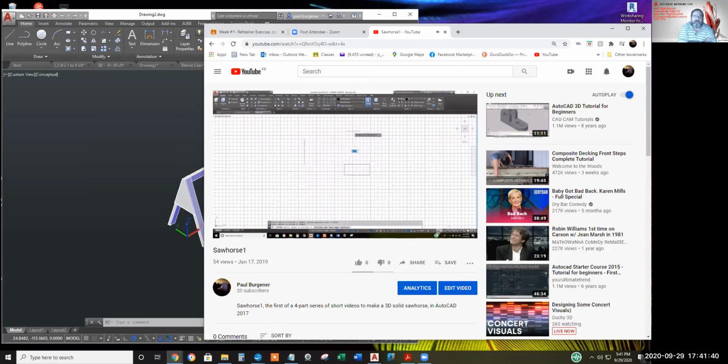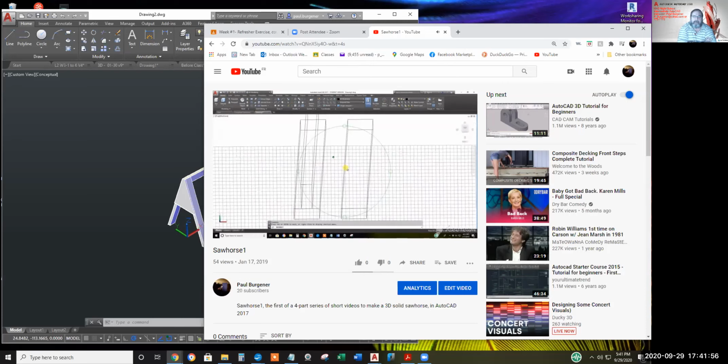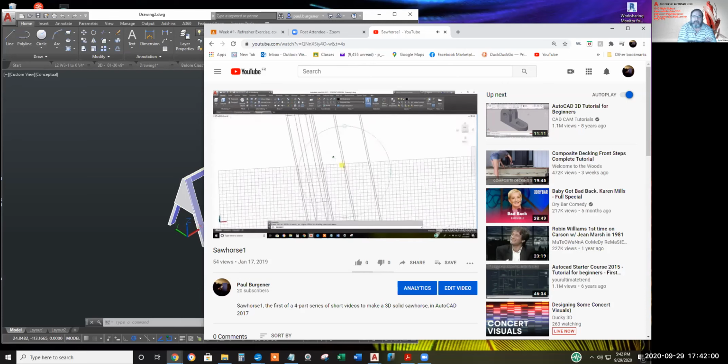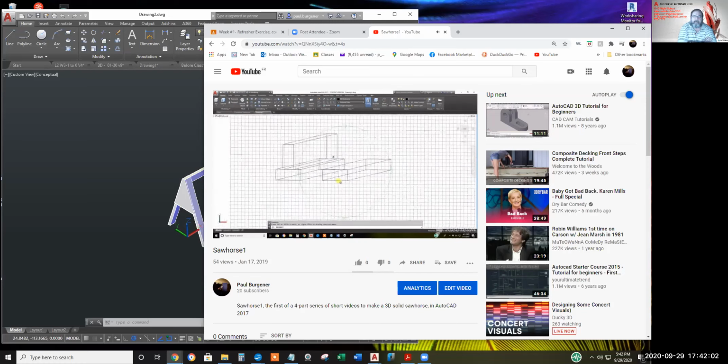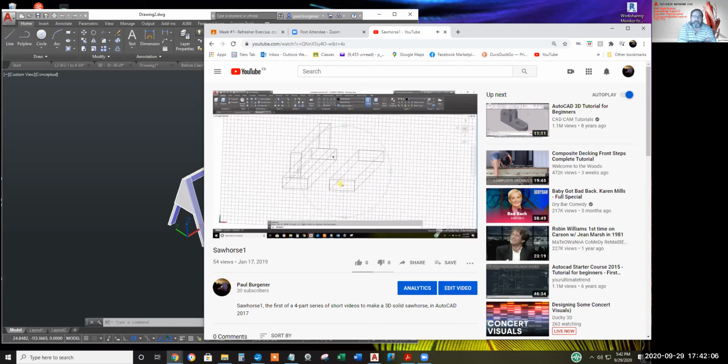You can also hit Enter by right-clicking and selecting Enter. Enter. 48 inches long. Free orbit. Now these three 2x4s stick straight out of the XY plane. Their ends are touching the ground and they're going straight up.